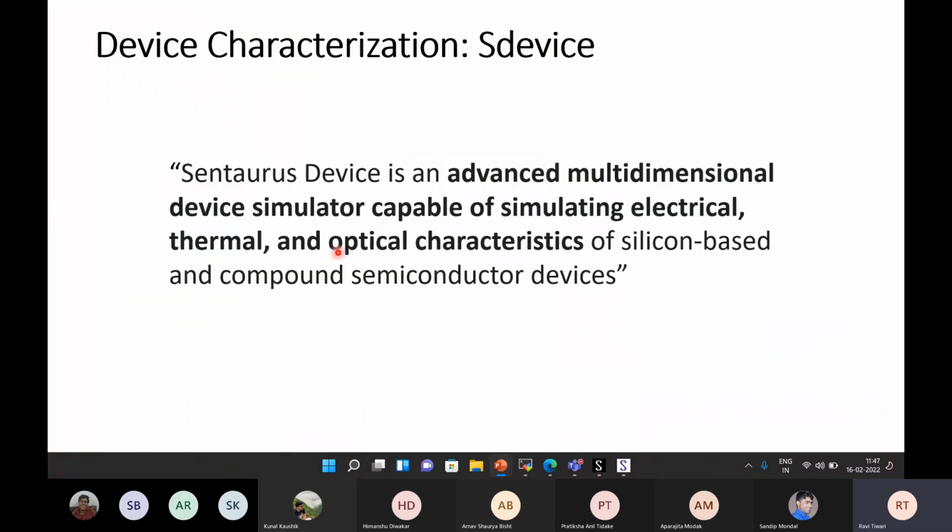In Sentaurus Device, you are going to apply some voltage to the device, where you have provided the contacts, the pink lines that I showed in the 2D structure of the MOSFET. There you can define some physics. You can define the temperature. You can define the voltage ramp conditions. You can select the fields you want to check during and after the simulations. Those all will be done in Sdevice.